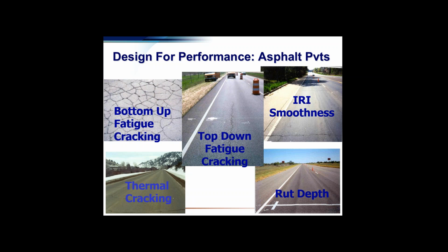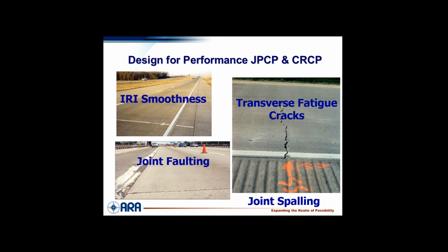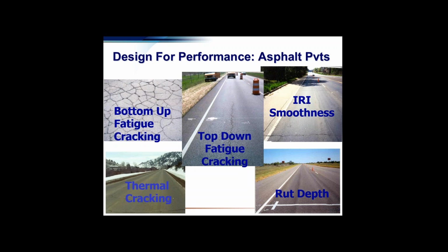The thermal cracking, and transverse cracking, low temperature cracking, rutting, permanent deformation, and smoothness. Those are the ones that were monitored. And there's others, there's raveling, would be another one that you could put in here. Block cracking might be another, and so on. It's mostly load associated. There are, granted, the supposedly just thermal, but I think this is also maybe contributed.